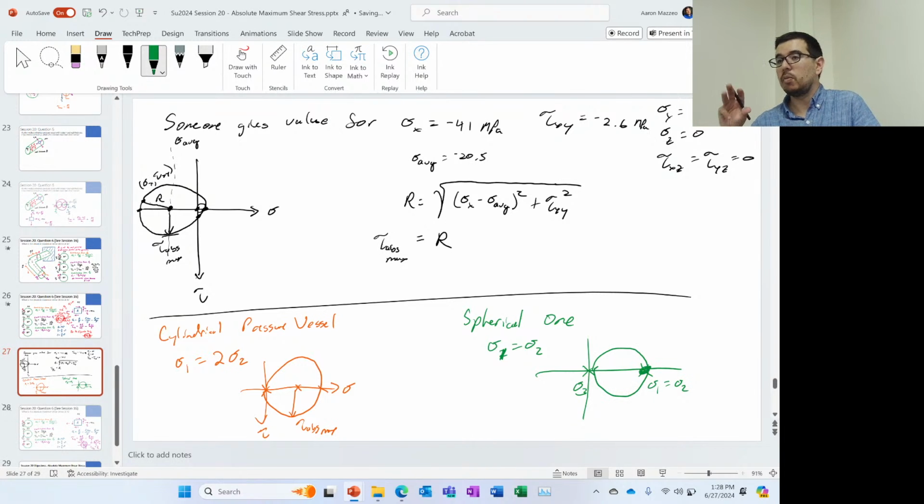Anywhere on that plane, you rotate about a radius coming out of the sphere and you're just still there. You have two axial stresses that don't change as you rotate about that normal component. But you have to look out of plane. You have to consider what's happening in the direction where you have a sigma 1 or sigma 2, 3. You have two planes to choose from, essentially, and that is where you're going to have your absolute maximum shear stress.